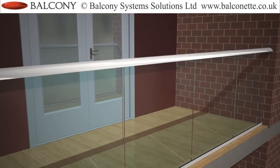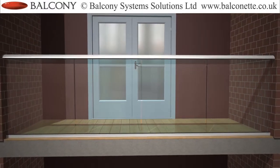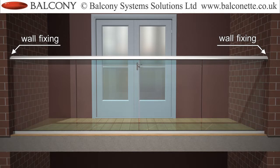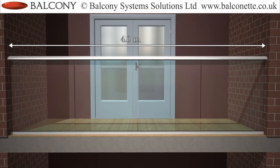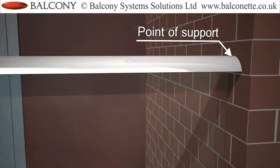The strength of the handrail and its rigidity determines the maximum span that the handrail can support. Therefore, if the handrail is fixed to the wall or structure at both ends, then the handrail of the Balcony 2 system can span 4 meters without the need for any vertical posts. The wall fixing is referred to in the report as a point of support.